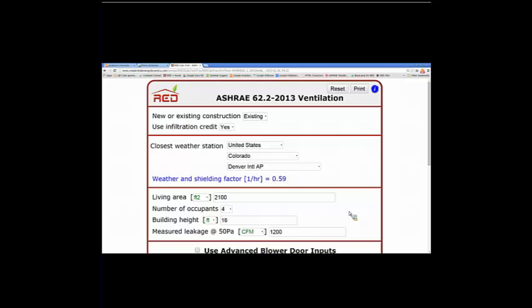If it's an open kitchen, the ASHRAE committee decided that you would therefore have to include the entire volume of the house for your calculation of 5 air changes per hour. You might very well end up with a very large number, leading you to the opinion that it would be very unwise to run the fan continuously.